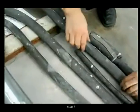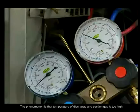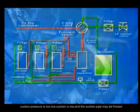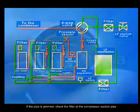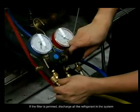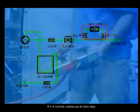Step 4. Check if the pipes of the low pressure side are jammed or deformed. The phenomenon is that the temperature of discharge and suction gas is too high, suction pressure is too low, current is low, and the suction pipe may be frosted. If the pipe is jammed, check the filter at the compressor suction pipe. If the filter is jammed, discharge all the refrigerant in the system and wash the filter. If it is ice jam, install a dry filter. If it is normal, please go to the next step.